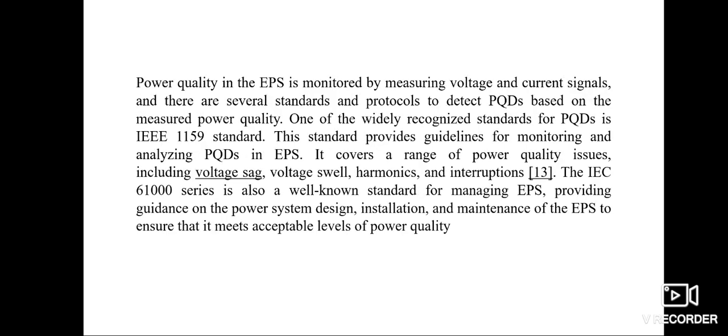Power quality in EPS is monitored by measuring voltage and current signals, and there are several standards and protocols to detect PQD based on the measured power quality. One widely recognized standard for PQD is the IEEE 1159 standard. This standard provides guidelines for monitoring and analyzing PQDs in EPS that covers a range of power quality issues including voltage